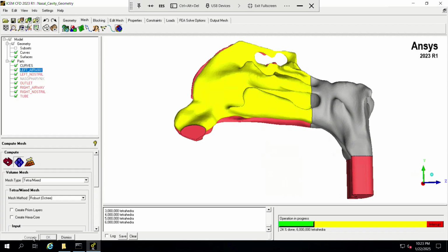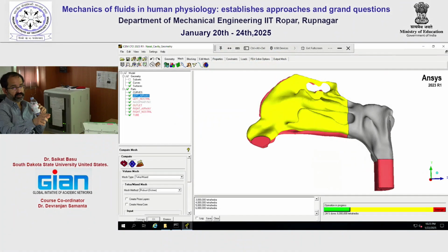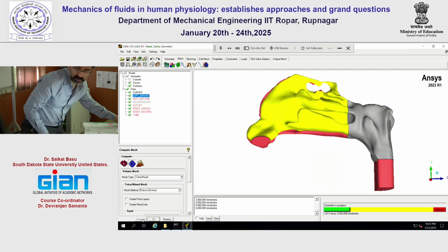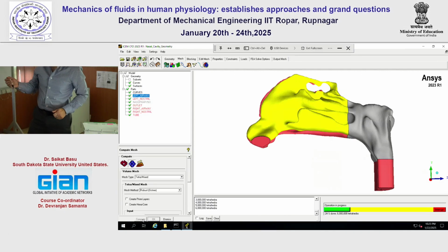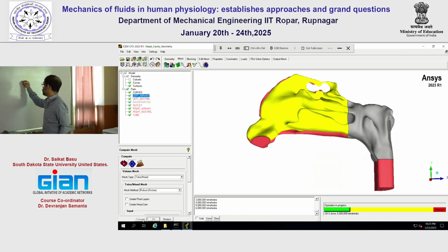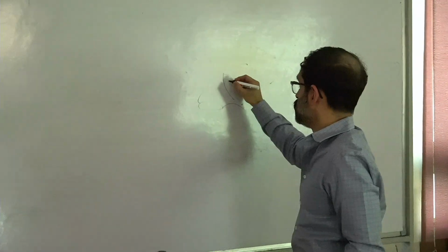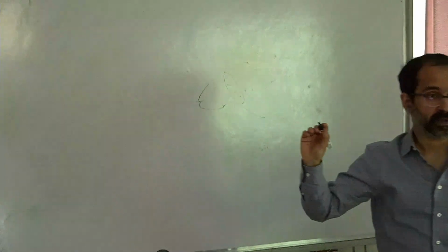No, this is not a solid region. Basically there is a cavity inside. This is not solid. This is just the shell. Yeah, inside is hollow. So you are building the mesh. That is a very good question in the sense that some students do have confusions with this. For example, here the STL is a shell file. So if you look at the cross section, it is hollow. It is not solid, right?